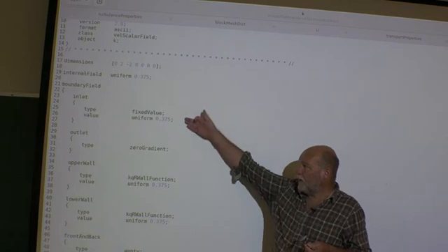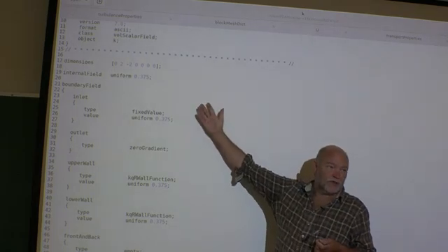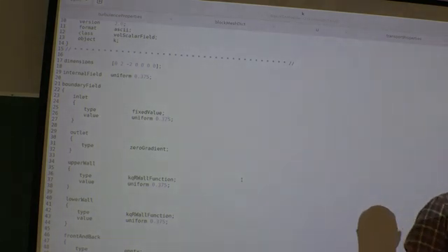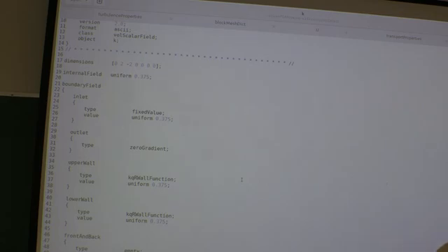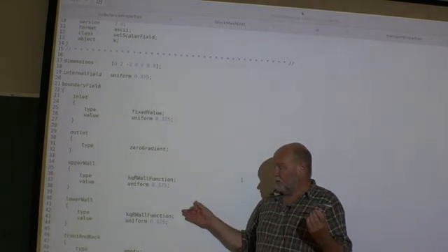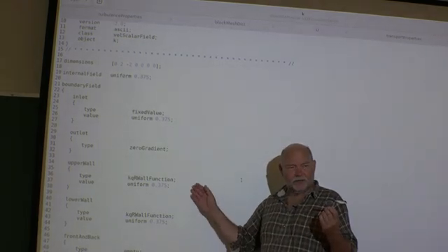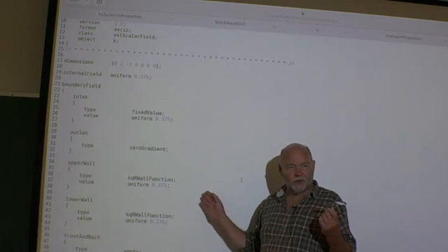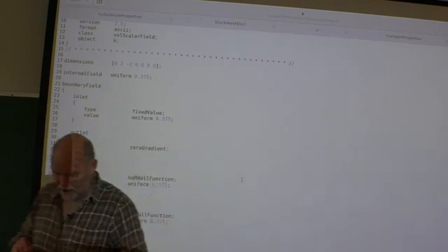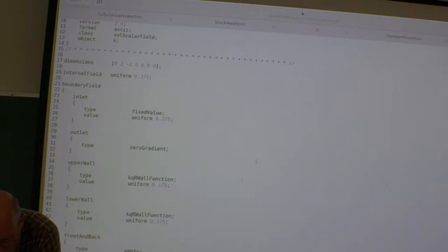Just give it a fixed value and then a very small number or 0. Well, actually, I won't recommend 0. Use a very, very small number, 10 to the power of minus 6, 8, 10, something like that. So we have to check after we have done the simulation, is it a match with the wall function or not wall function, and the y plus along the walls? We have to have a look at that one.